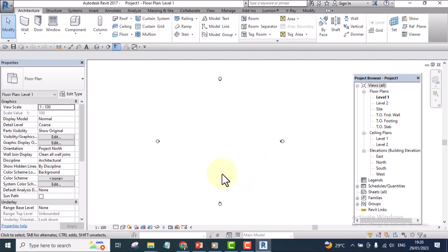All right, okay, now let's see. This is it here. Now you see these four things, we call them elevation markers. This one is the one that snaps the front elevation, that is if your front is facing here. It doesn't matter the size of your project, your project should be done within these elevation markers.